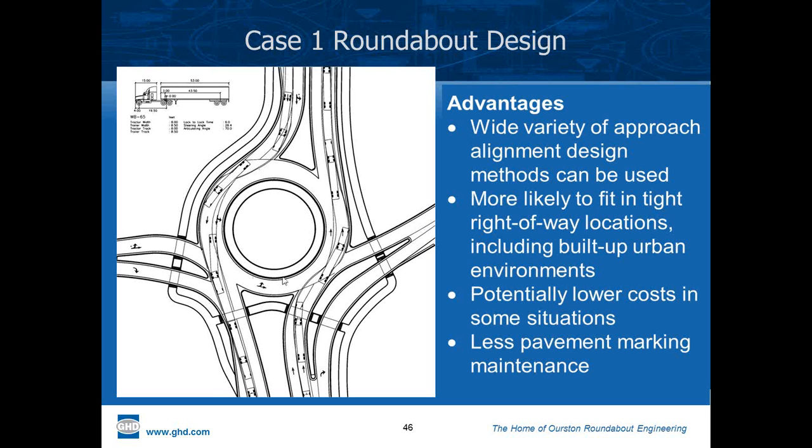And there are some roundabouts, quite a number actually, in North America. It surprised some people to know that there are 20 or 30 unstriped roundabouts in existence, some of them for close to 20 years now. And they are basically all Case 1 designs. So the truck driver enters, seeing no striping in the circulating lanes, with no pavement arrows either. They just take up all the space they need, and often will prevent other drivers from getting in beside them by keeping on the right-hand side and making sure that if someone can pass them, that they can see them on the left. And we've spoken to truck driving companies about this sort of thing, and we get different responses, but generally they like to be able to take up as much of the roadway as possible and prevent traffic from getting beside them.